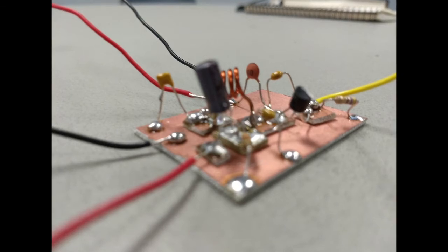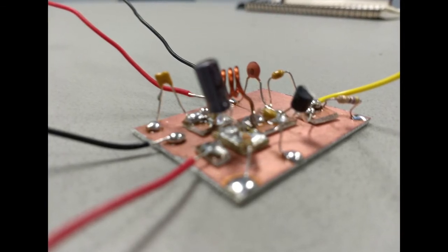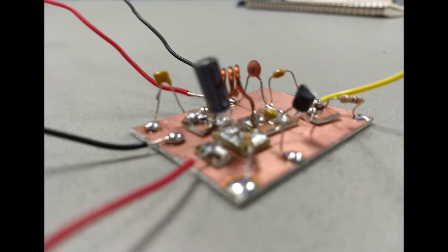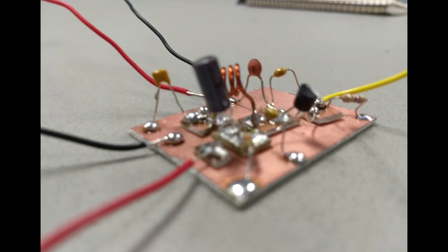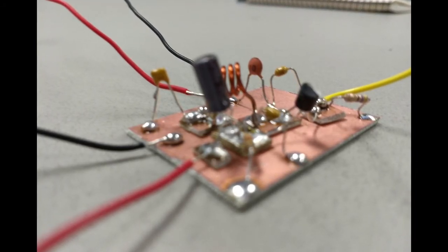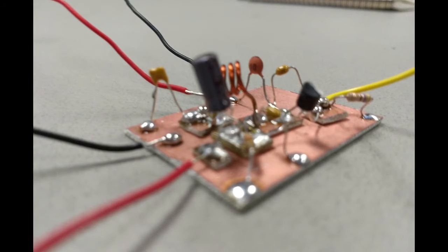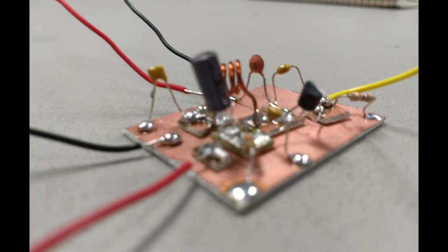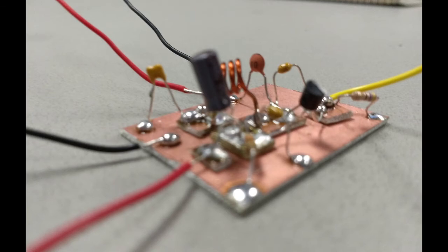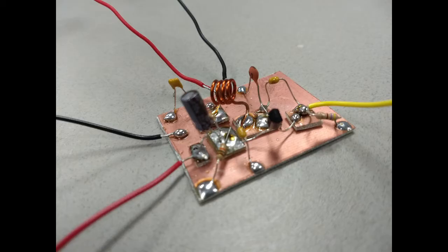We faced a few complications in this circuit project. The first construction of this circuit did not function correctly as we believe we used an incorrect resistor value in the initial build. Poor soldering may have also resulted in the initial failure as we may have neglected to properly strip the varnish off of the copper wire that formed the inductor.